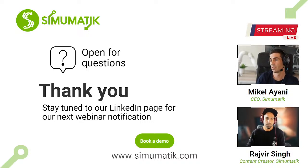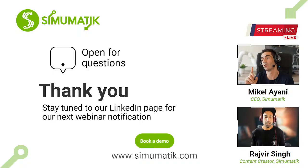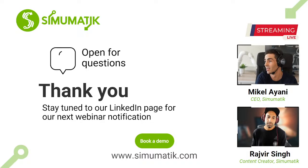Sounds great. And again, like usual, if someone is interested in integrating Simumatik with a platform that doesn't have it and maybe wants a more native protocol, you can always contact us and say, I want this. I don't know, Mitsubishi PLCs, they have OPC DA or whatever standard which we support, but there is also something native which has better performance. Like with ADS, why we have ADS is because of the performance. It's way quicker than OPC UA. So for some applications, it's much better to use ADS.